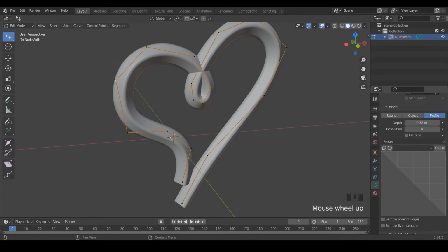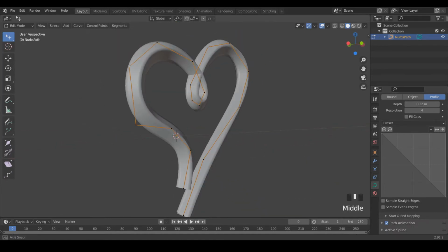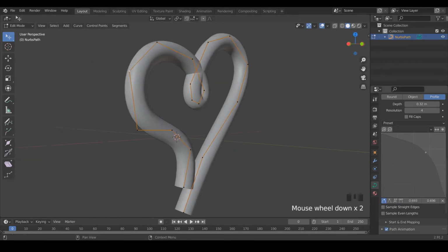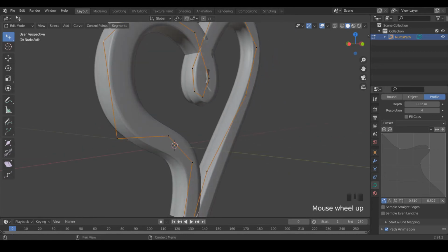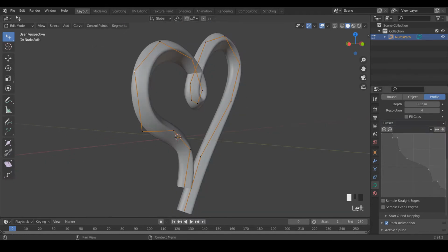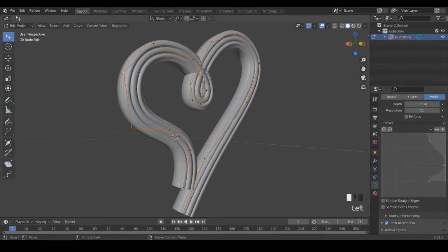And with this one, there's really a lot of freedom to go through and tweak the look to really get some custom shapes in your curve. You can see if I start pulling around these points in this graph to the right, I can really start building up some interesting shapes and kind of play around with the look that I'm going for. And if we click on this drop down, there's even a short list of presets that you can play around with that has things like crown molding. And if you bump up the resolution just above the graph, you can really start to get a sense for the detail that can be achieved with these shapes.